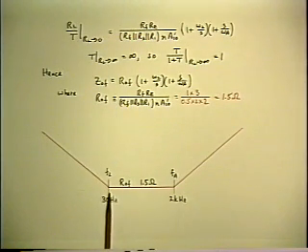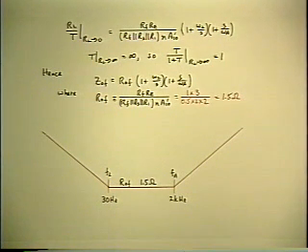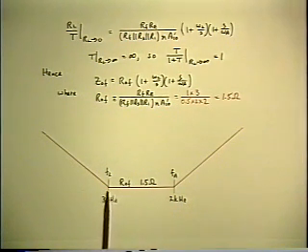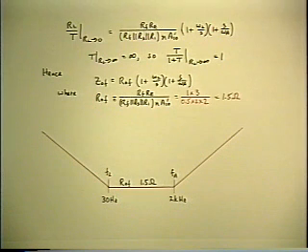And it rises when the loop gain starts to fall. Notice the closed loop gain was flat from 2.7 hertz to 22 kilohertz. But the output impedance is only low over the much narrower range over which T is large.